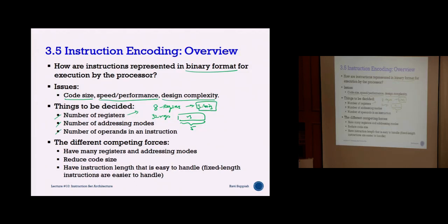And that means if I still have my full 32 bits for my full instruction, and instead of 32 registers you only need 8 registers, you free up potentially 6 bits, correct? For RS, RT, and RD. So now this additional 6 bits, what are you going to do? You can think of other things that your processor might be able to do.